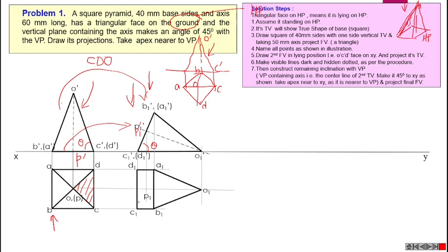That condition satisfied. Then again, in top view, we can't see C1 dash O1 dash. That slant height is not visible. Similarly, D1 dash O1 dash slant height also is not visible in the top view because these visual rays can't touch that line. That means those slant heights are not visible. Then we can draw those slant heights as broken line in top view. Then finally, the axis is always chain line. Axis is always chain line. This is the secondary condition.